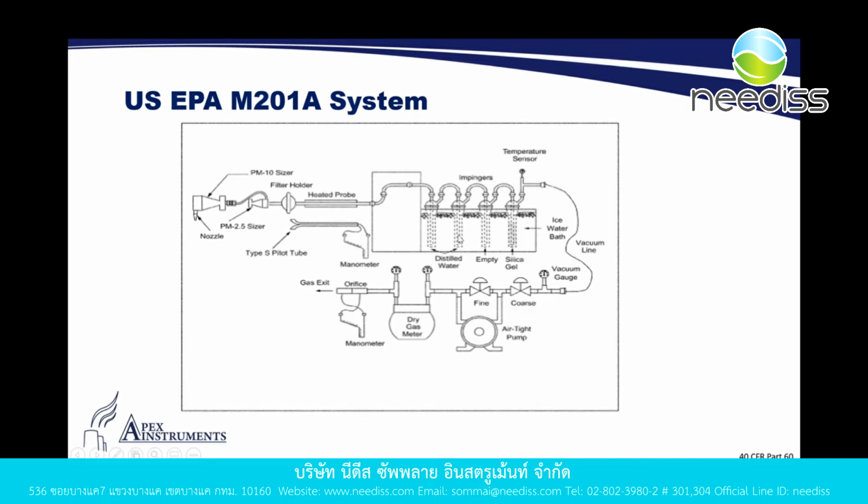that if for some reason you were to have a sudden surge of vacuum come through the system, maybe you have a blockage at the nozzle and all of a sudden it removes, it falls away, and you have a lot of extra vacuum suction coming through the system. This will actually prevent the silica gel from coming up the arm, down the sampling line, and into your console. So it acts as a safety mechanism to have just a small amount of glass wool put in this last impinger exit arm.